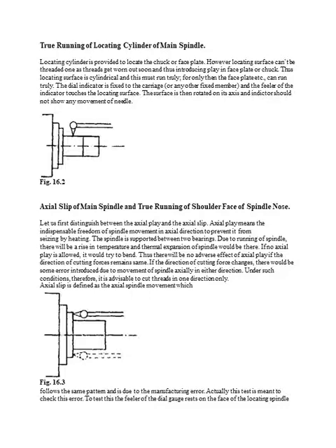There are three reasons for axial slip to occur. One is error in the supporting bearings, then the face of the locating shoulder not in the plane perpendicular to the axis of rotation, and irregularities at the front face. So due to these three reasons there will be some variations. That variation should not be there. That is the purpose of this test.